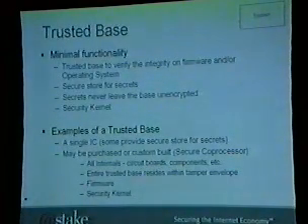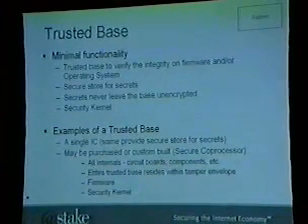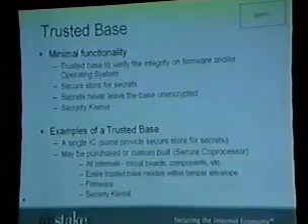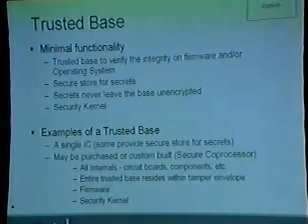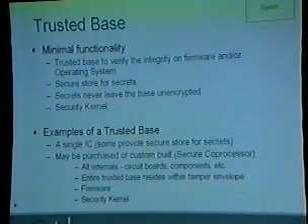But he approached the problem of protecting the secure coprocessor by layering the tamper methods. They used epoxy, they used this nichrome weave. They actually had one weave around it, and then they wove it a different way. And I think they had 3 different layers of weave. So if you tried to go in at it at any different angle, you would probably sever something and get busted. It would also zeroize certain things out.